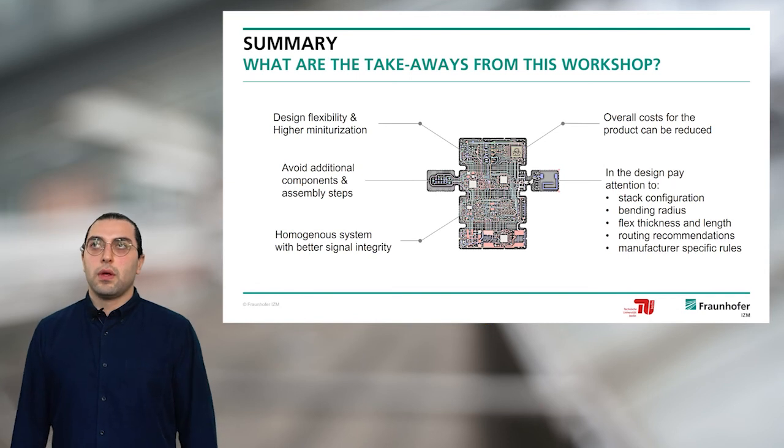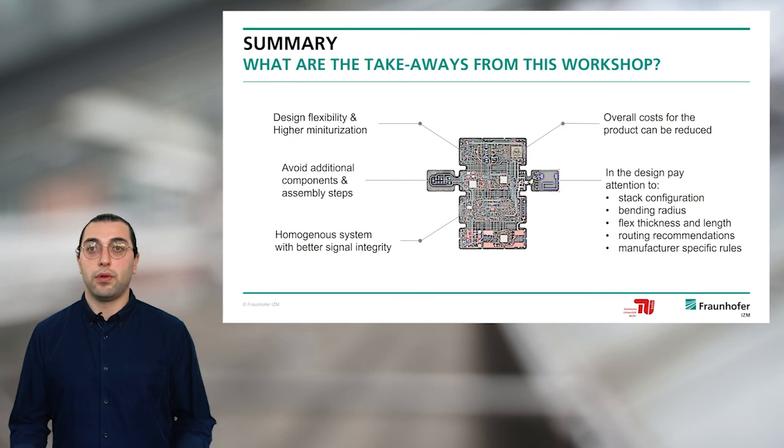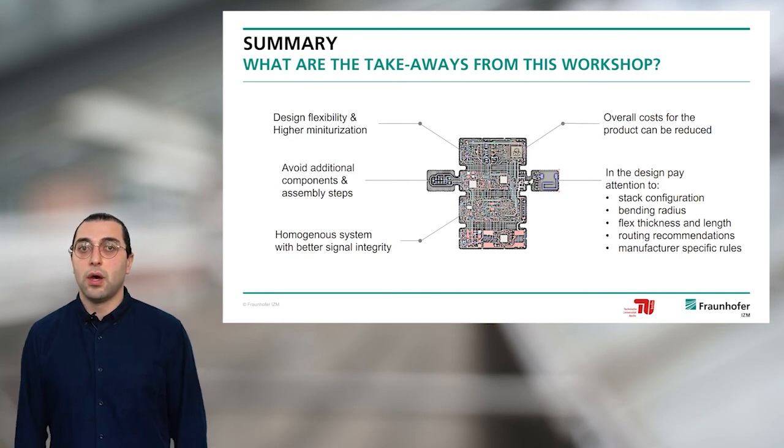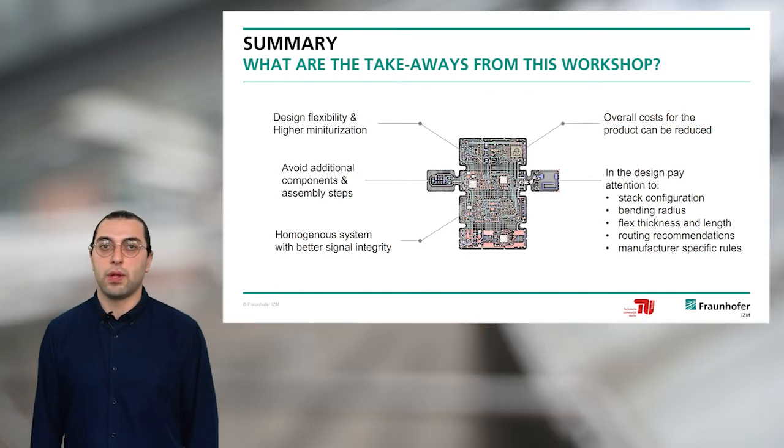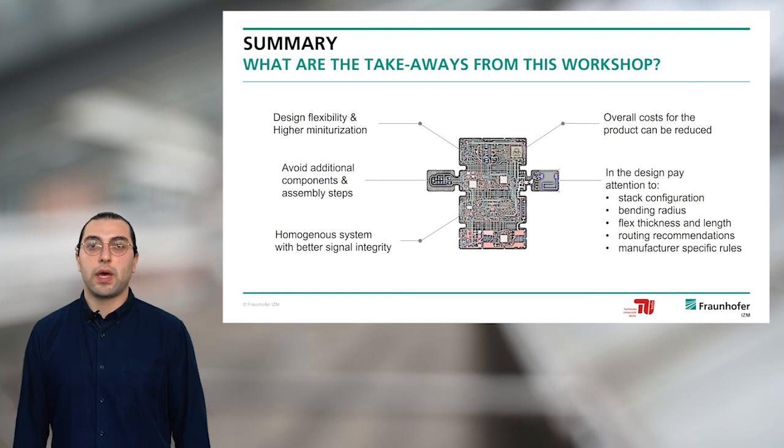You should use rigid flex technology when you want to have a higher design flexibility, so that you can, for example, place components in different directions, like sensors, or if you want to have high miniaturization, then rigid flex technology is one solution. We can also, with rigid flex technology, avoid additional components and assembly steps.